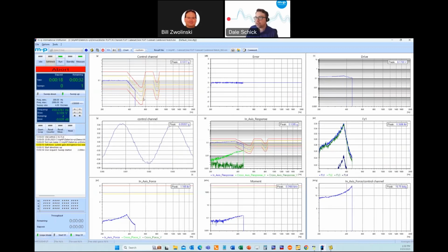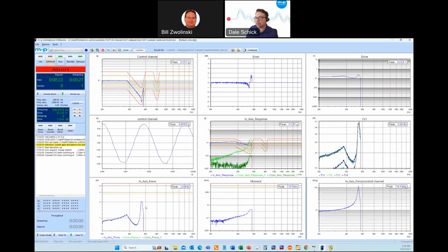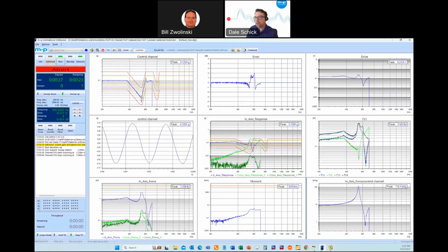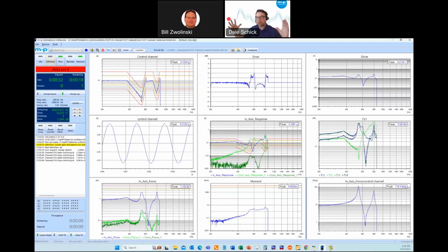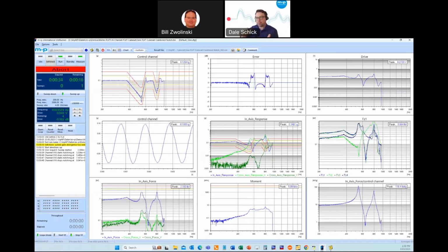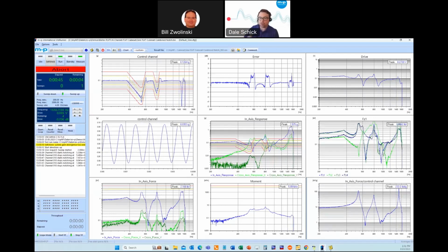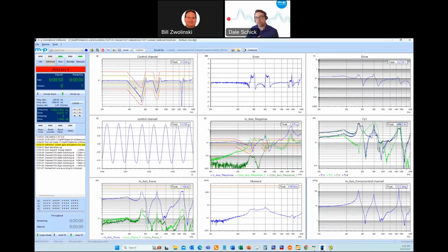And here we are approaching. And here is the handoff. You can see we did cut it off there. But if you can imagine, if this tried to hand off, and you have a very large, complicated system with a lot of inertia, the acceleration input is going to be at its lowest it possibly can be on the table. But your force response is going to be at the highest it can possibly be at the table. So giving the control to the force earlier in this bathtub notch is a better idea because the signal is much, much better.